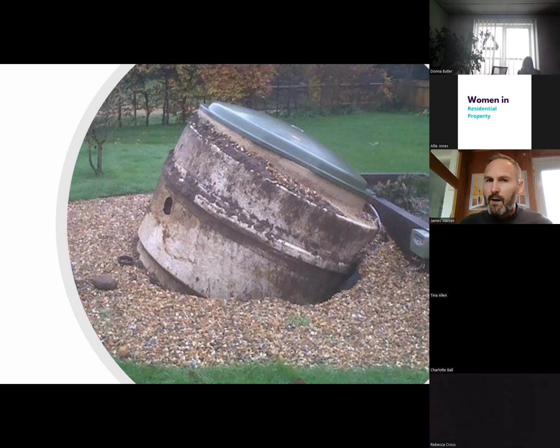What should happen is that the experience of the emptying engineer should come into play when they start to drain down the liquid level. If they hear any creaking, if they start to feel the ground move a little bit, they should stop their activity immediately. They should refill the tank with fresh water to create that equilibrium of pressure, and they should go from site. Come back maybe in a month, 6, 8 weeks, when the ground's had a chance to dry out, and this will not be a possibility. So it really is down to the competency of the engineer that attends in that perfect storm, in that perfect set of conditions, as to whether they should continue that emptying activity.